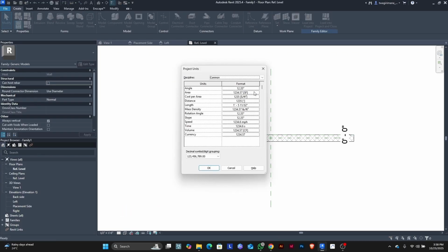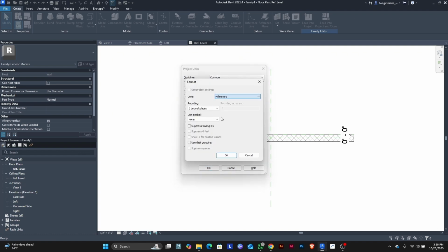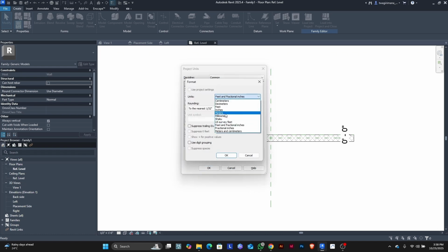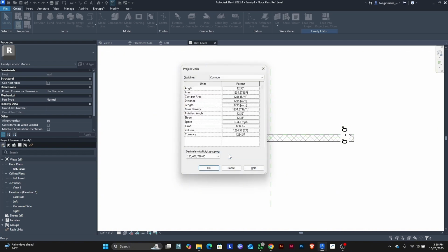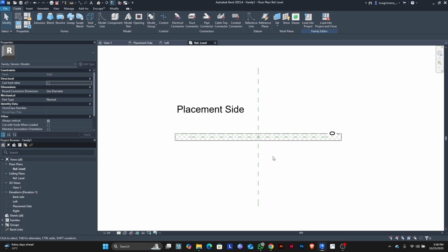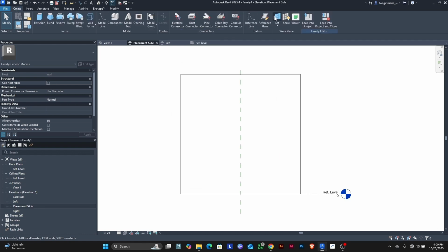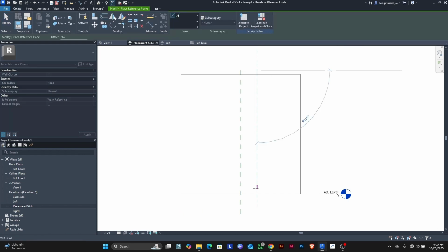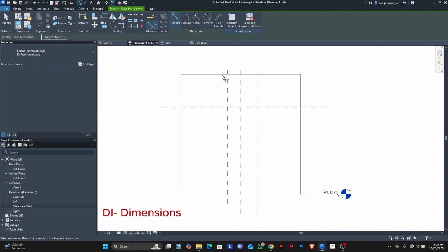I will start by choosing the generic model wall based, since our bookcase will be on the wall. As always, we have to change the units. For me, I go with millimeters for both distance and length measurement. This bookshelf will be parametric, and of course will be a Revit family.